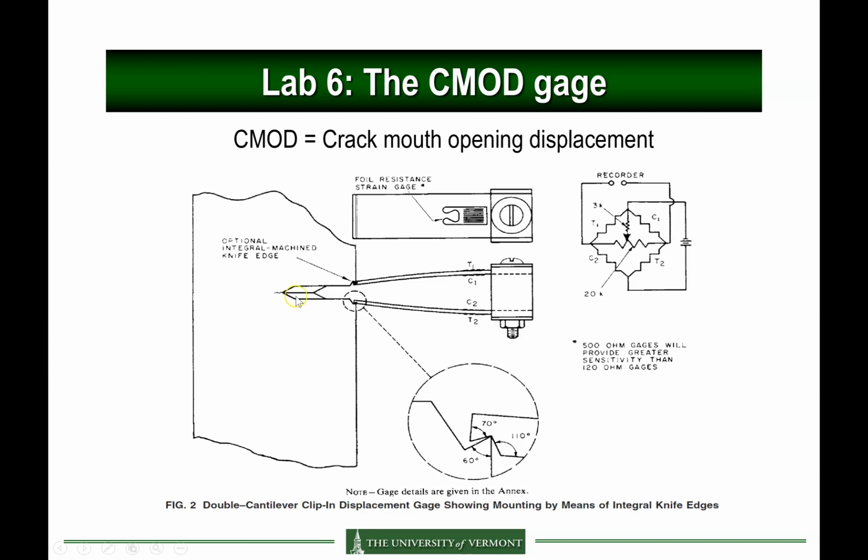All right. So when we open the crack, this is going to measure a positive opening from this position, and then it works as a standard extensometer or like a strain gauge. It will be measuring a resistance. We have a quarter bridge setup, so pretty much like your strain gauge experiment in lab number, I think that's lab number 2, where we collect the strain from the deformation of the beam here.